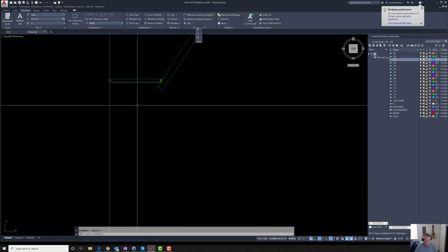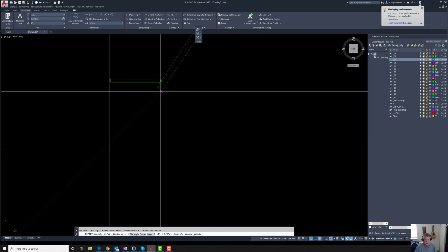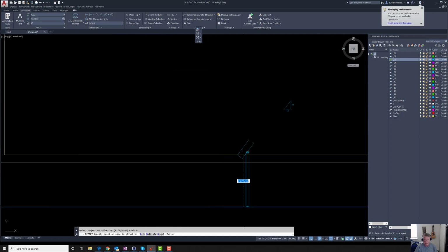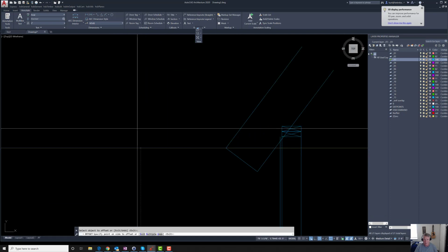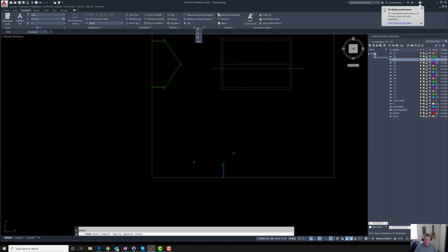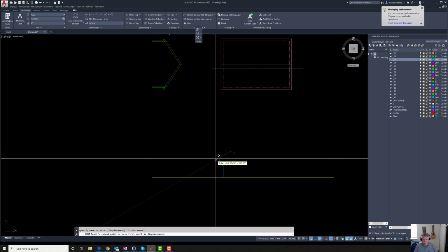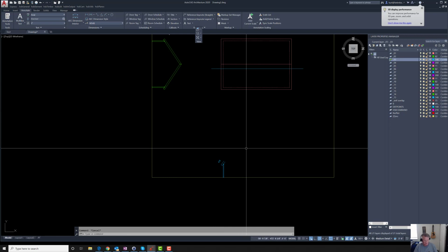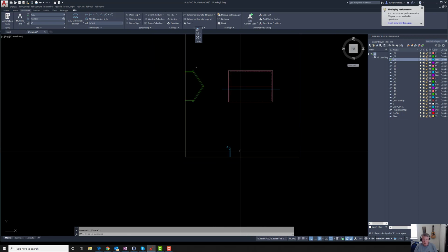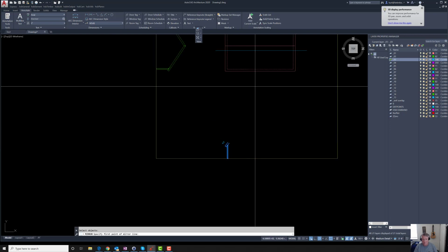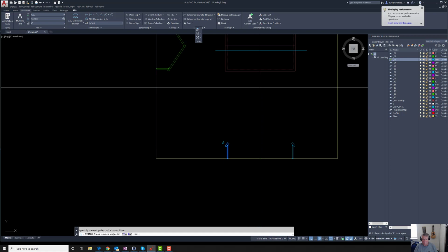But I do know that I have the fascias lined up again, because real quickly again to show you, it's even height, the corner of the fascia here, which I think is one of the most important things that's driving this design. So now we'll use the same method we used a few minutes ago to mirror this over and connect the dots. So why don't we just do that first right off the bat here. We will mirror this from the center line of this building over here.